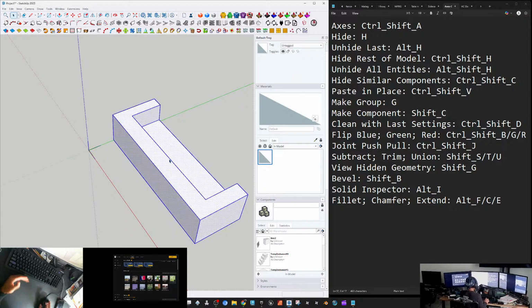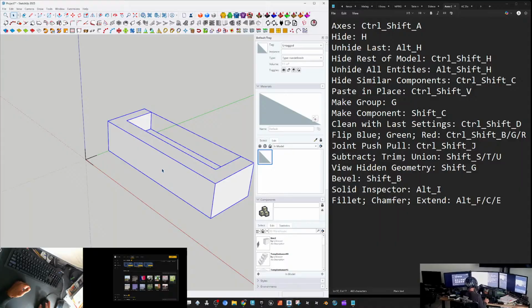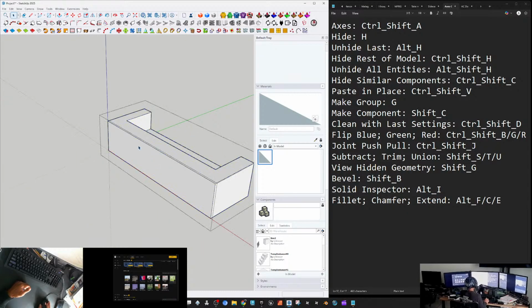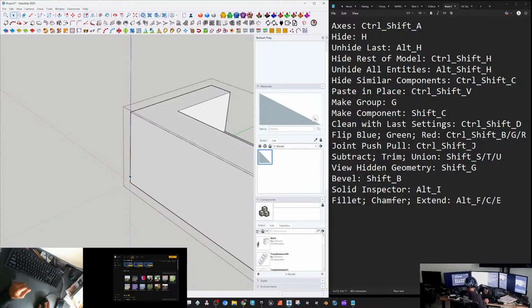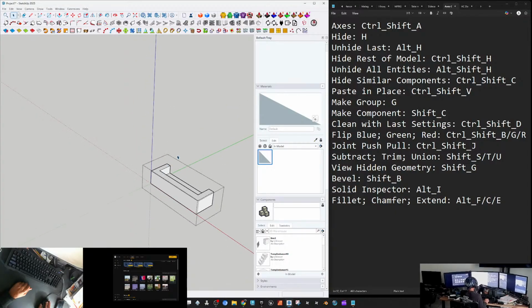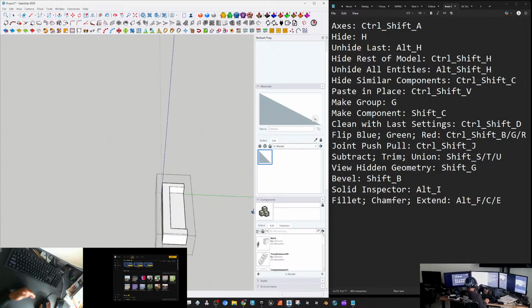So I'm going to triple click the couch and press G to group it. And then when I click into that group, double click into it, you'll see that my new origin is at the edge of this group. Now, two things I could do. I could do a Control Shift A, which is a custom shortcut, to then place the origin in a new position. I want this origin to be in the center of the couch with the couch facing forward.